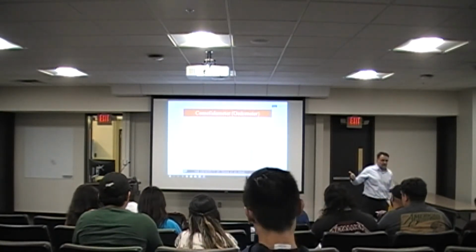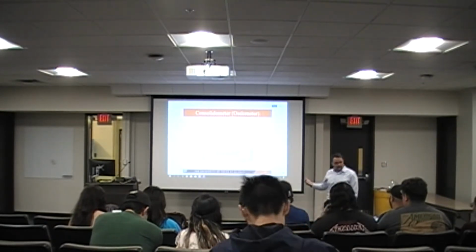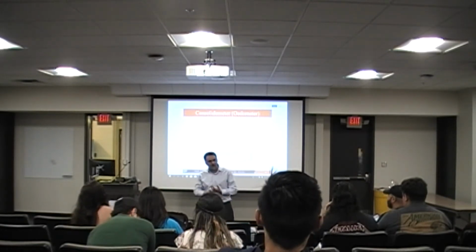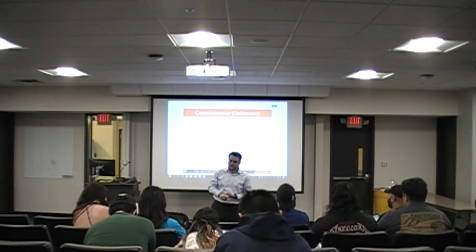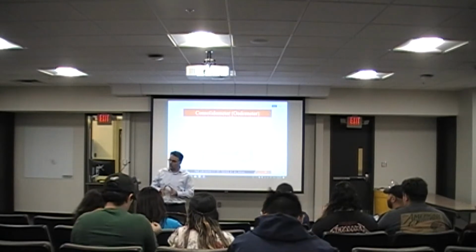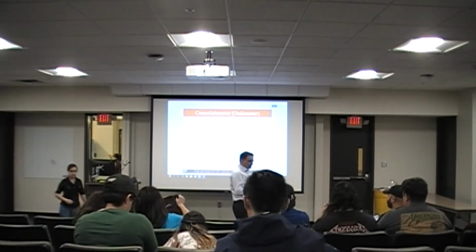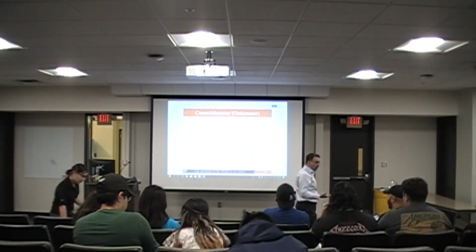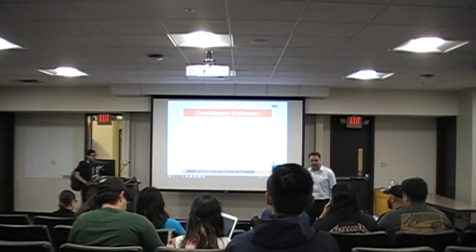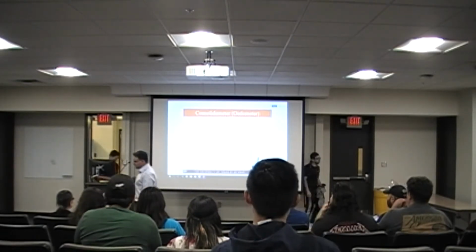You know the geostatic stresses, right? The geostatic stresses are stresses associated with the weight of the layers of soils, right? So for that, all you need to know is the unit weight and the height of the layer, or thickness of the layers, right? How do we get the height of the layer? Simply you go and get that in the field based on the boreholes and the observation wells that we have. Now, for the unit weight, you get the material and you figure out what the weight is, what the volume is, and divide them by one another, you get the density of the material, and based on that you can calculate the unit weight.